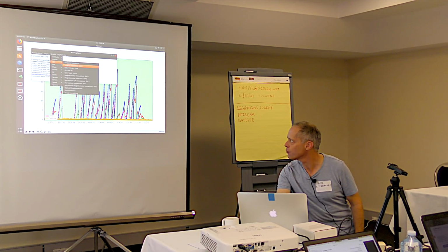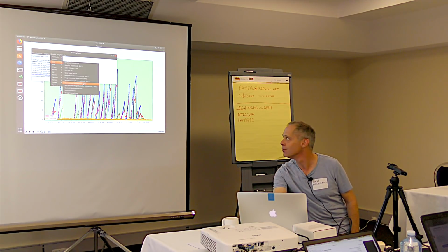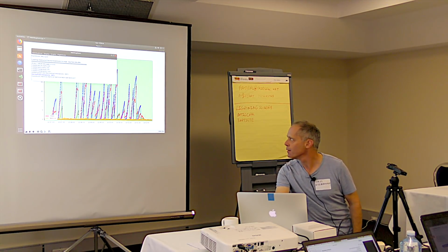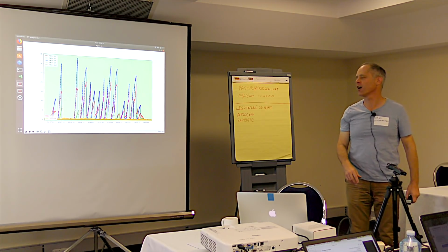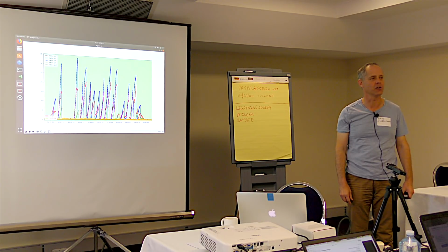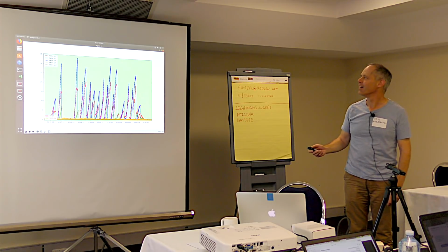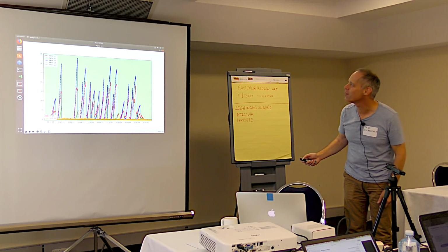Go to EKF. And these are normalised innovations, EKF2. Now, they're normalised because anything over 1 means the EKF has failed that sensor and is refusing to use it. And, well, I'm sorry, Peter, but you've managed to hit almost 35 there.